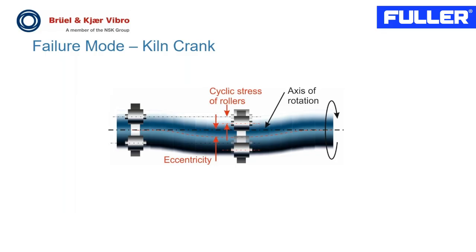This issue can be caused either by mechanical erection tolerances, but it can also be due to thermal effects in the kiln. And the thermal effects are what's most relevant, because this is something that is changing over time, and this is something that is being affected by the operation of the kiln and the process inside the kiln.